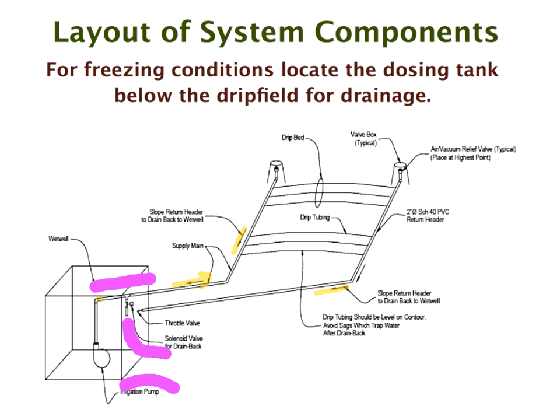And here they've used the throttle valve instead of a solenoid valve. This throttle valve could be another solenoid valve, or it can be a continuous flush, as it is in this case. In which case, you save yourself a valve and make the controller a little simpler, as we spoke about continuous flush yesterday.